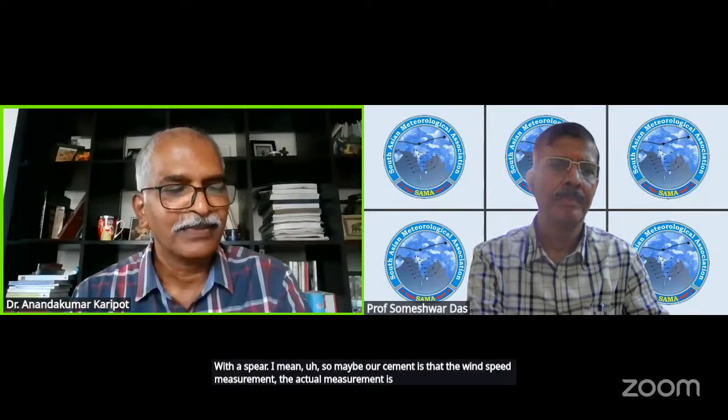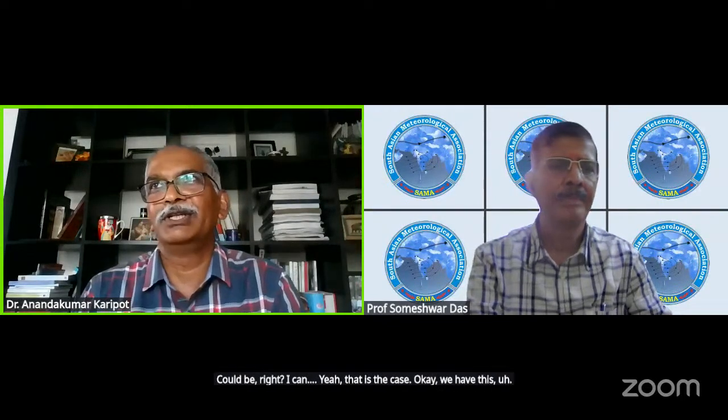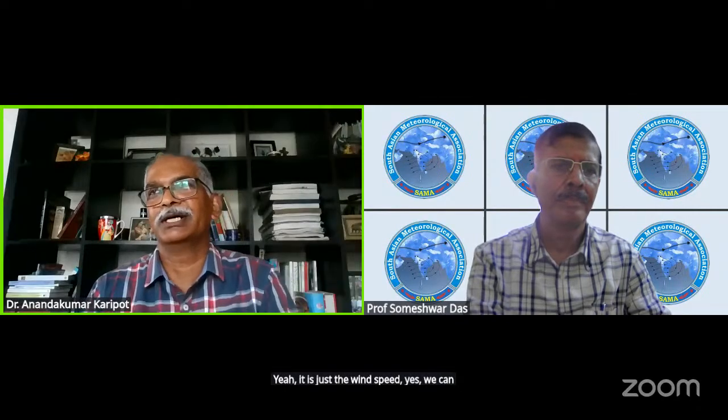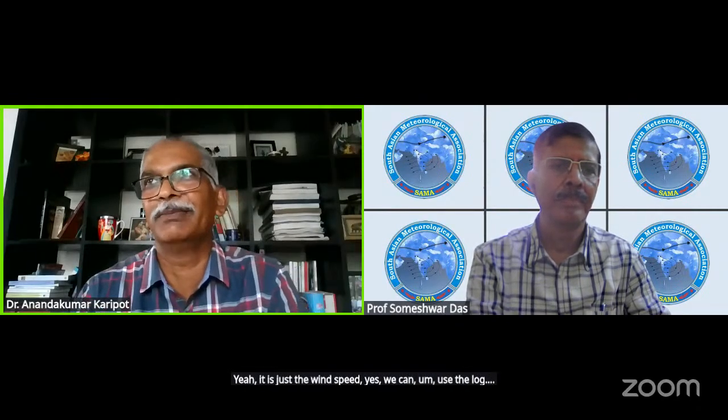Maybe what she meant is that the actual wind speed measurement is at 10 meters, but we want to estimate the wind speed below 10 meters. Yes, sir, that is the case. Okay. If it is just the wind speed, yes, we can use the logarithmic wind profile relation, which says the wind at any height, u, is u star by k times the logarithm of z by z0. That is again for neutral stability.